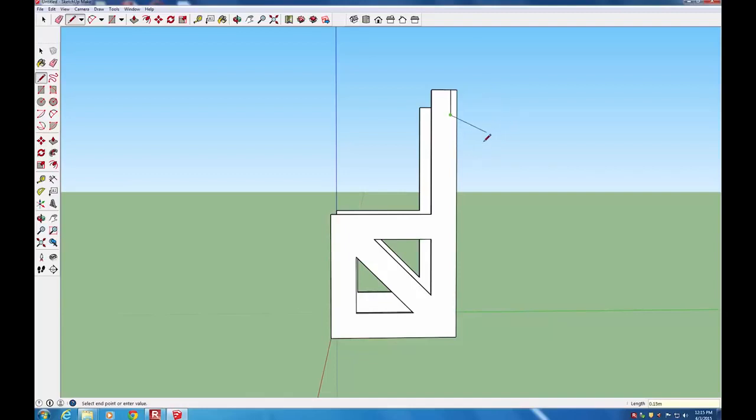And if you're in the line tool and you want to start drawing lines again, but you don't want to start from this endpoint, you can just click Escape on the keyboard, and you'll stay in the tool, but it will sort of forget about that last point you were on. The next spot we're going to go from is down here. We're going to go up 0.025 and over 0.025. And then Escape, and then same on the bottom corner. And so now we have these three guide points that we're going to use to place the rectangular cross pieces.